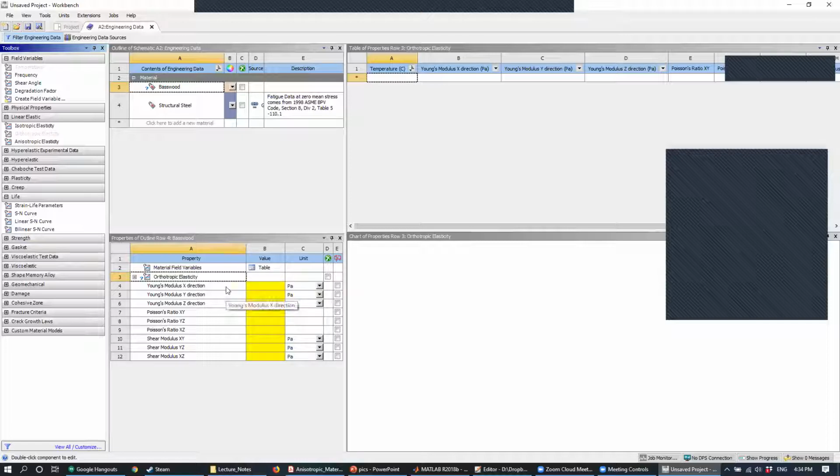Right, so the question is, it's not trivial to calculate the inputs for the orthotropic or anisotropic material, so it's always better to look them up. Yeah, that's definitely true. With these material constants, it is really difficult to come up with these, especially with your own calculations. So if you can look up your material online, that'll tell you these constants, or you look up some kind of research paper, which is what I did. I have a paper that's referenced in the handout that you can look up for wood specifically. So if you can use data from there, then I would input it straight from the data sources and try to limit the amount of calculation that you do.